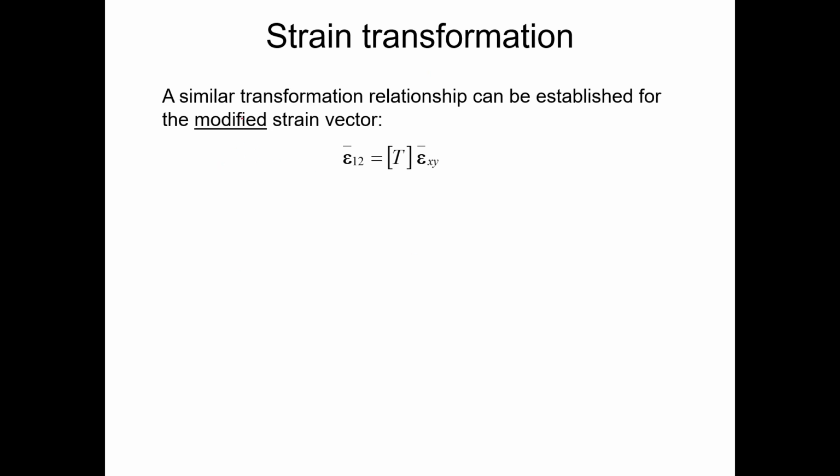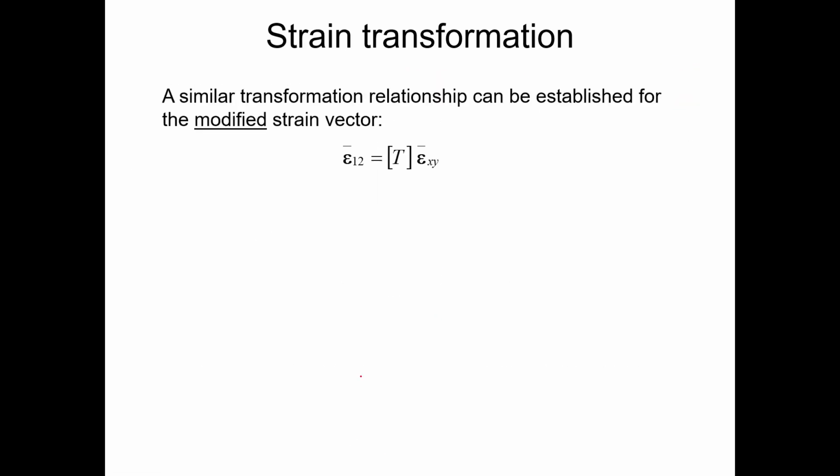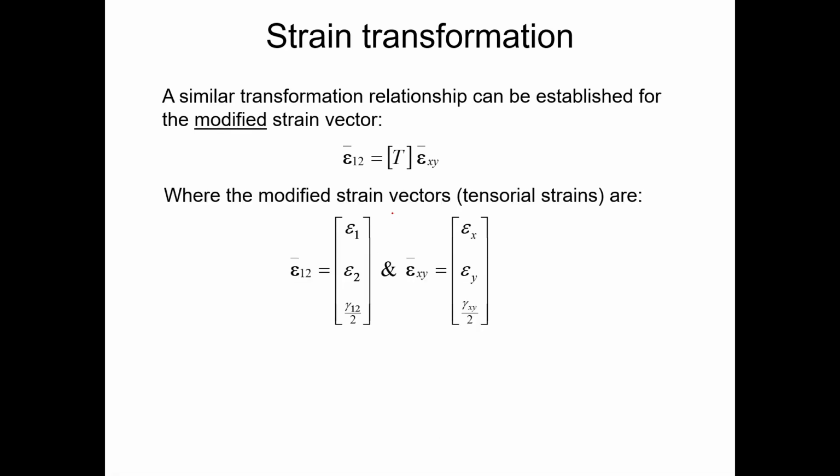We can establish a similar transformation relationship for the strain, where epsilon 1, 2 is equal to the transformation matrix times epsilon xy. If you go back, you'll see this is the stress and this is the strain.